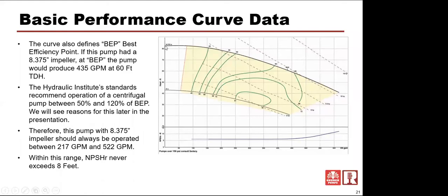So it's there to help you try to diagnose, and we'll talk about deadheading a pump later, because generally in a system, the only point you know that it's operating on this curve is at zero flow. When it's absolutely no flow, that's about the only point in this curve in a system that you know where it's operating. So we put it there to give you some kind of approximation from a troubleshooting standpoint.